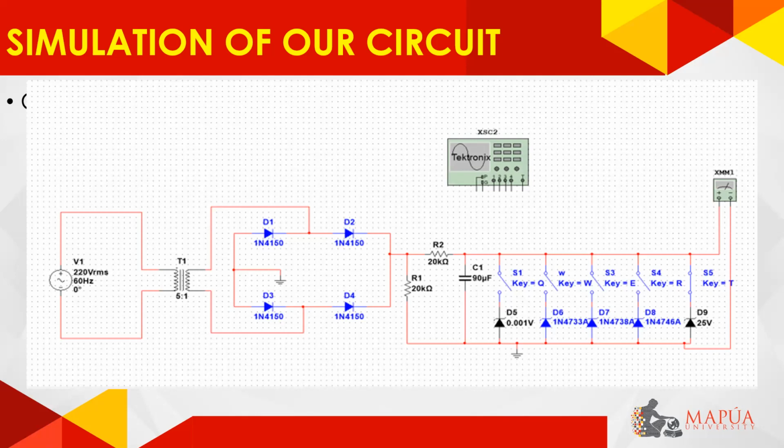In this project, we learned to create a basic DC power supply that produces a constant voltage to all loads. With the right Zener diode models, we were able to obtain the values of 0 volts, 5 volts or approximately 5.009 volts, 8 volts or approximately 8.118 volts, 17.931 volts, which is approximately 18 volts, and 24.949 volts, which is approximately 25 volts.